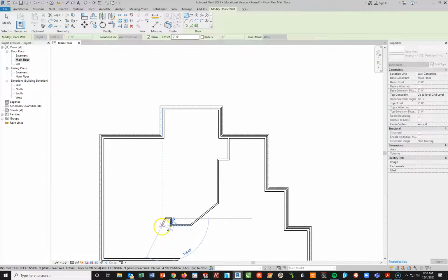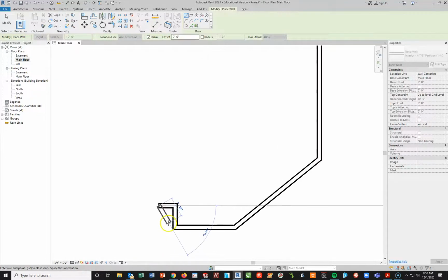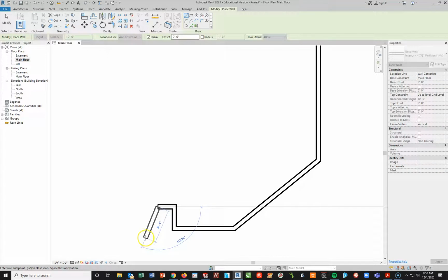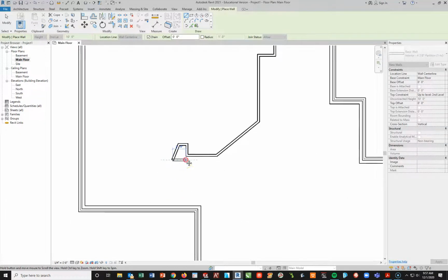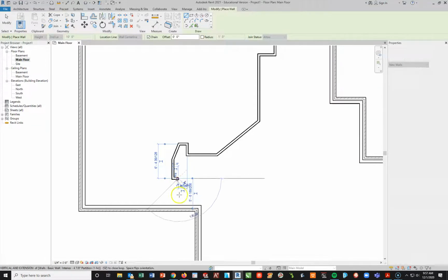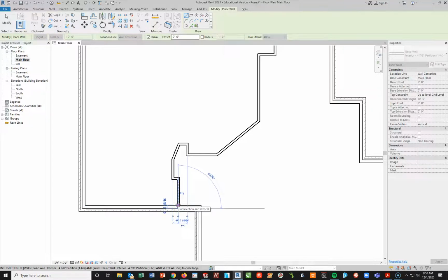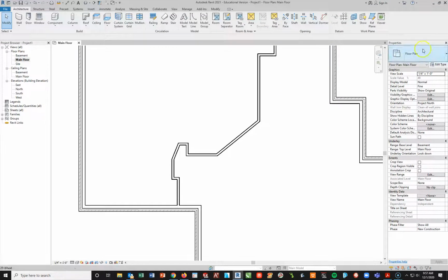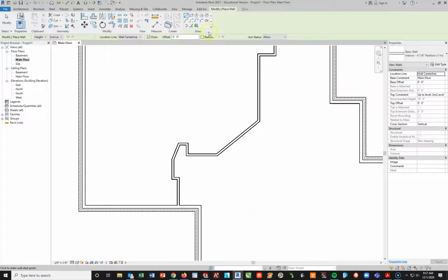And again, if you're looking at the plan, you will understand what I'm doing here. Let me blow up on it real big so you can see this. And this is where you've got to play around. Backing up, pull this down. You can see I'm a little bit off already. And then from here, I'm going to draw a wall, let's say just barely in, and then straight down to this wall here, okay? I'm going to hit escape to turn my wall off. Escape deactivates basically the entire wall thing, okay? If I go back in, I can turn your line tool back on and continue from here, okay?